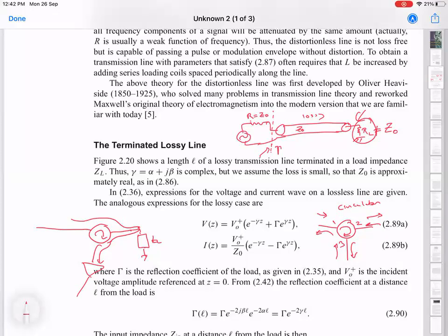So here the return signal is not going past the same path. The important point here to note is that the fact that the incoming signal is attenuated is no longer a detrimental thing, because all it does is that it reduces the amplitude of the signal that is incident on your device. You control that. And if you want a certain amount of power to reach your device, you put correspondingly larger power. If your attenuation is say 60 dB, you put the right amount of power at room temperature, so that the correct power is reaching your device.